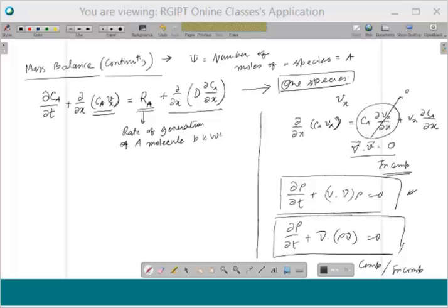So in that case, that's completely a physical phenomenon, which is flow of a single phase, single component fluid, and the right hand side would turn out to be 0, no reaction, no diffusion, whereas generally the flows involve reaction and species basically chemically transform from one kind to the other kind. And that will lead to concentration gradients, and that will lead to diffusion. So diffusion will be important. So this is the most general form of mass balance equation in a flow system which may possibly be undergoing reactions.